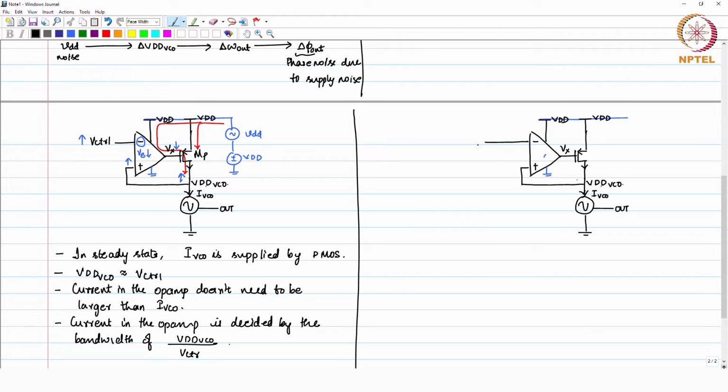So, you will have the charge pump loop filter which is connected to the charge pump, right, like this, and this is controlled by up and down pulses with the help of PFD. So, PFD drives this, and the inputs of PFD are your reference clock and the feedback clock.